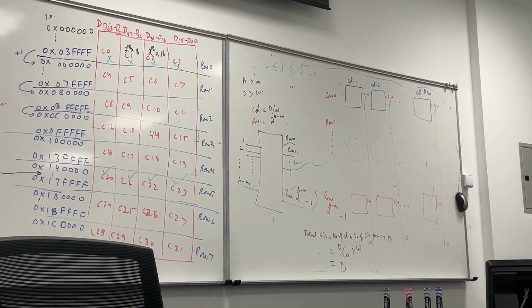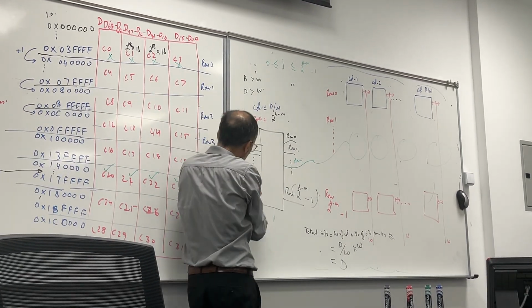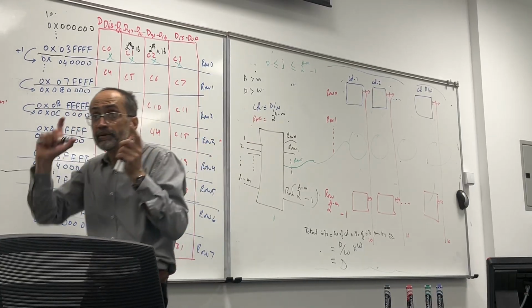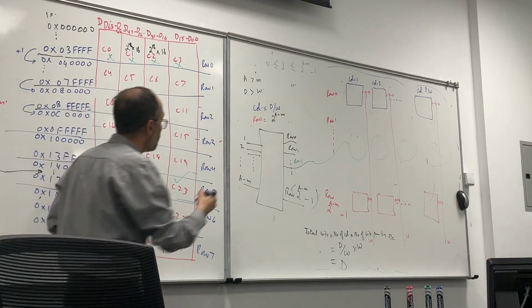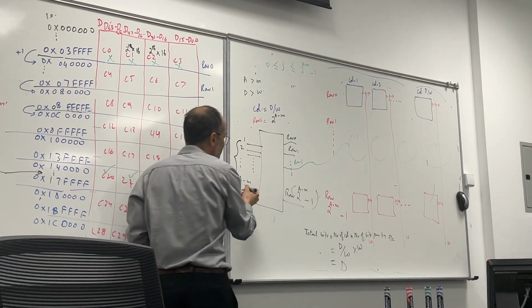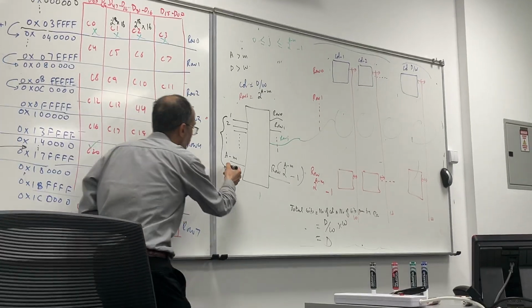Got it or not got it? So it will be enabled. Let's assume we have a binary, so we need to convert this J based on the binary of the most significant bits. Here, will the most significant bits of the address line or the least significant bits from the microprocessor side be connected? The most significant bits.